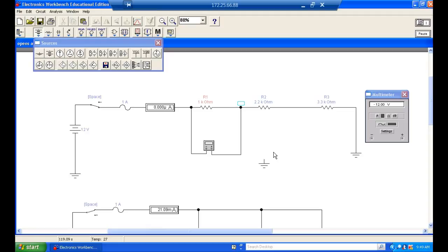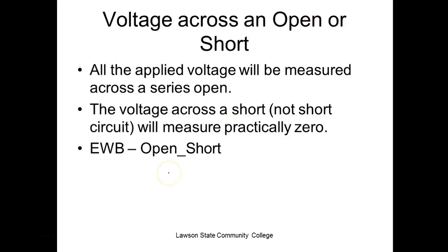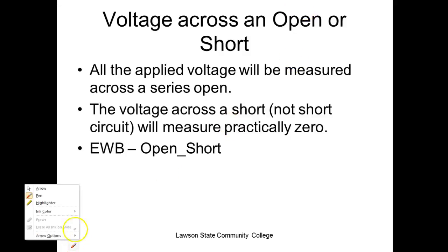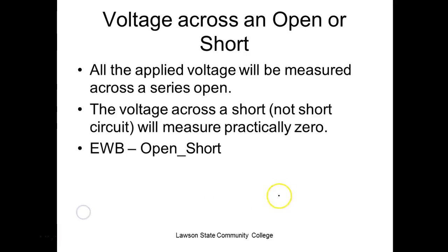Well, how many volts would it measure across the light switch with all these things on? Oh my goodness. Well, let's see, how much resistance does a switch have? Nothing. So V is equal to 1,000 amps times nothing. So how much voltage is dropped across a closed switch?